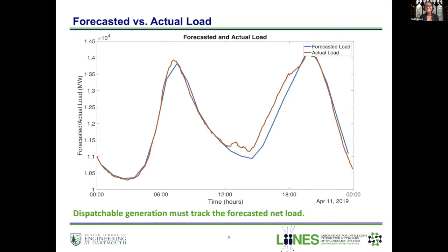And so that shift, but you definitely had huge switches between residential load, commercial load, and industrial load, with commercial load down at those times. I think in New York City, it was down about 14%. And upstate, it was like 5 to 6% down, but you're right, it was the peaks that were off. And that really also affected the energy prices. So even though the peaks were only off 5 to 10%, the energy prices were 25 to 35% off. The whole report that the students did is online, but you're right, this is really interesting to think about how something like COVID affects it.